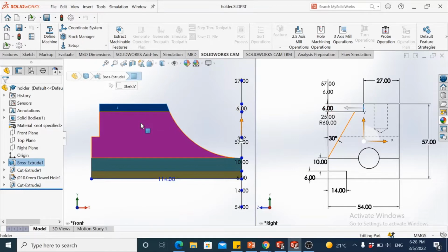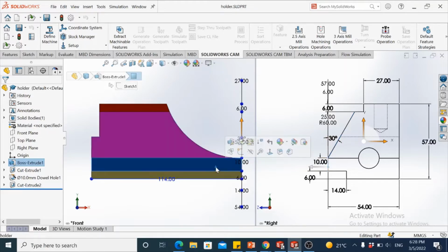The second face that we have here, when I pick up this, the top and the bottom of these contours correspond to the inclined line here at 30 degrees to the vertical. So what we see here is a foreshortened size of the shape that would lie on this inclined edge that is shown in here. Lastly, second last, we have got a surface here and projected onto the right side. It corresponds to the height of 10, the vertical edge that we see.